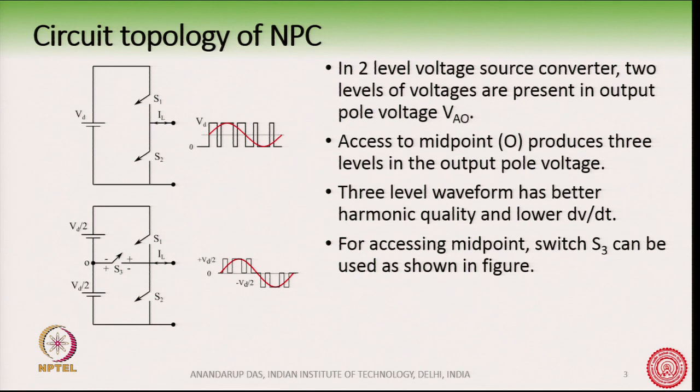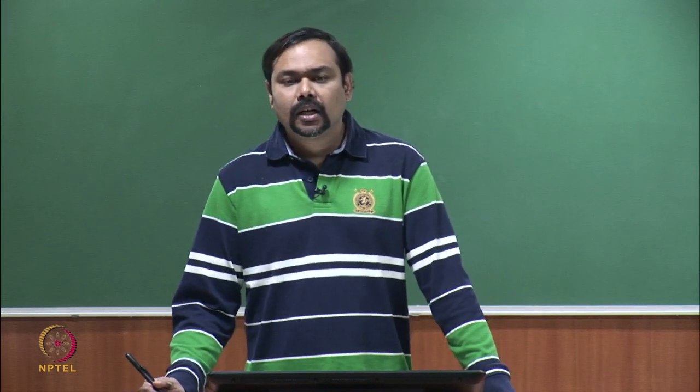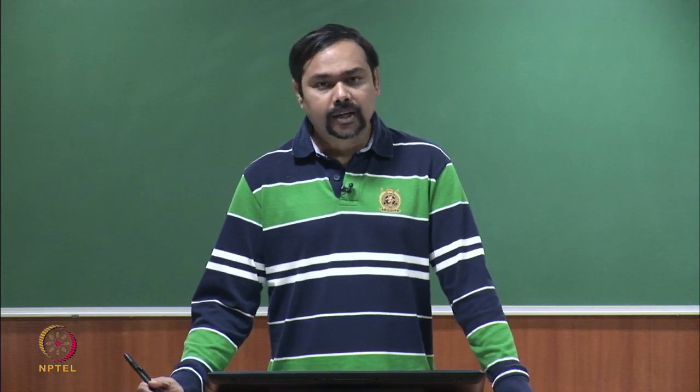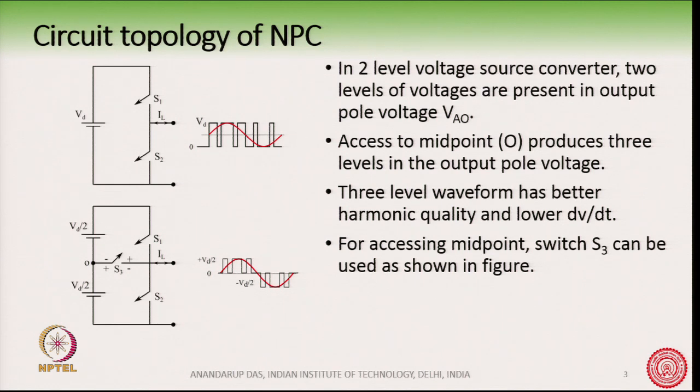which we have earlier said, and that is why some people go for a multi-level converter in its design. One drawback is that we need a high switching frequency of the switches, so that the size of the filter is reduced. If you do not have a filter, then sometimes the dV/dt on the motor, for example if this converter is driving a motor, can be quite high, especially with a long cable.